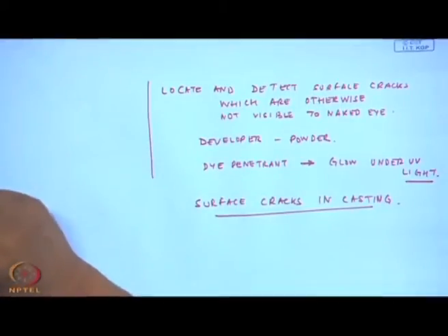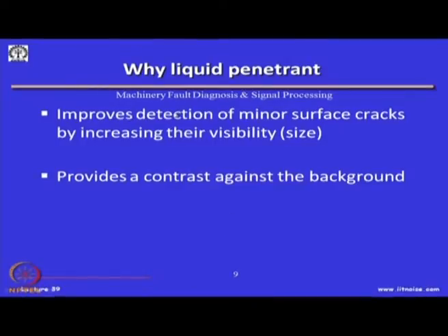So, why do we use liquid penetrant? Because it improves the detection of minor surface cracks by increasing their visibility and size, okay, and it provides a contrast against the background. Usually, the background of a material is very dull.